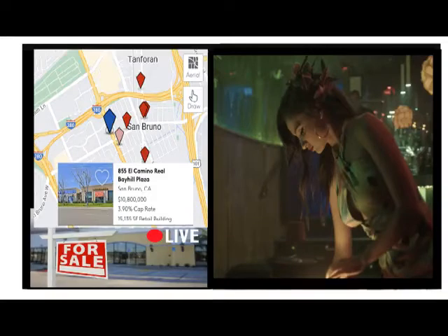Figure 14.4, Wall Framing with Platform Construction. Stud, top plate. Corner bracing: use 1x4 let-in bracing, steel X-strapping, rigid steel braces, or structural sheathing such as plywood, flakeboard, or oriented strand board. Sole plate, plywood subfloor, stringer, joist, anchored sill plate, foundation wall, header joist, window sill, window header.